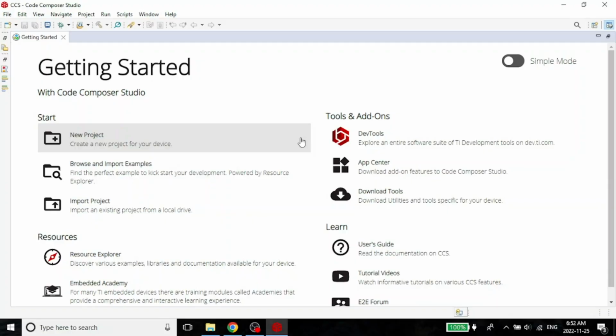I hope your kit is in exactly the same state mine is, with those few glowing LEDs that I have shown. You should see those LEDs, because otherwise it probably means that your kit is either not connected properly or not powered up properly, or maybe the control card is not inserted correctly. Alright, so make sure that you are in pretty much the same state as I am.